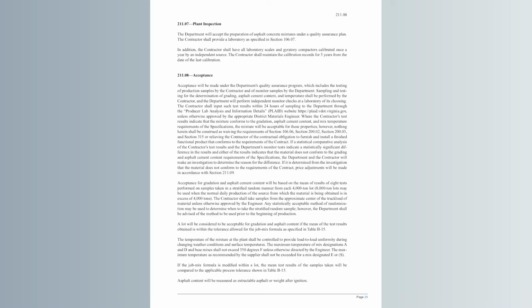That is unless otherwise approved by the department district materials engineer. That is a specification requirement. That is something that the department monitors very regularly. Acceptance for gradation in our asphalt content is based on the average of 8 tests for a 4,000 ton lot, and a lot is considered acceptable if the test results are within the tolerance allowed for that specific job mix formula.